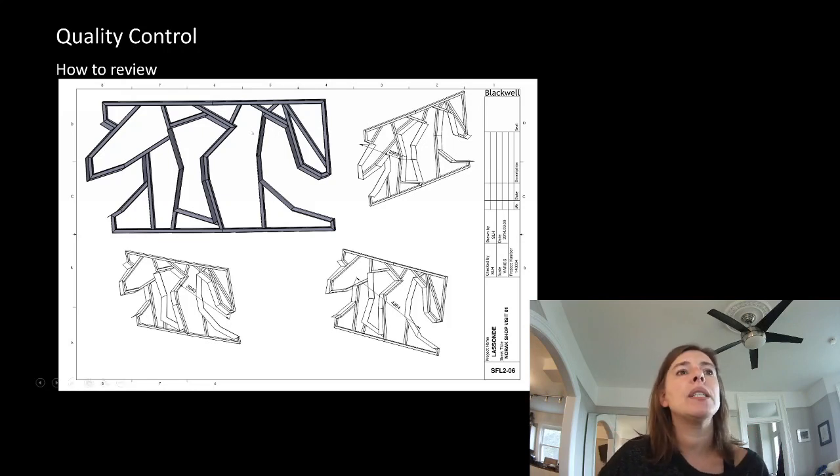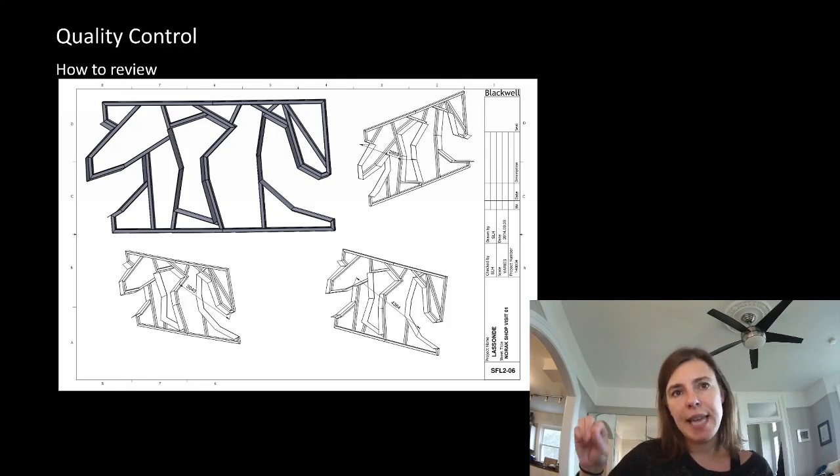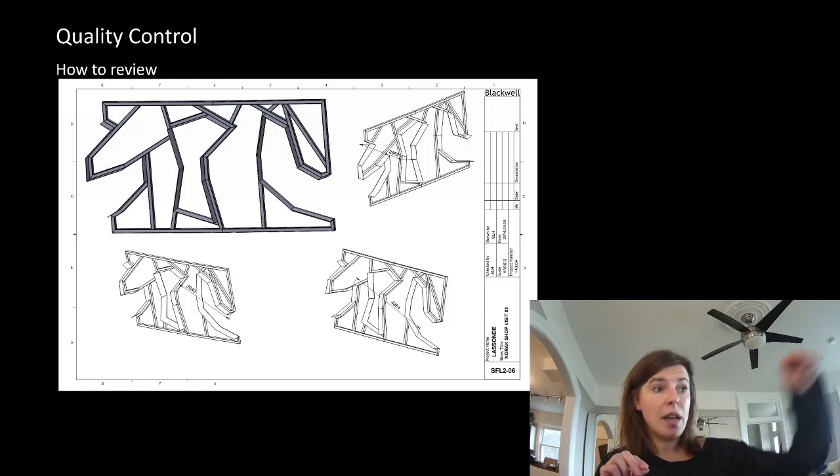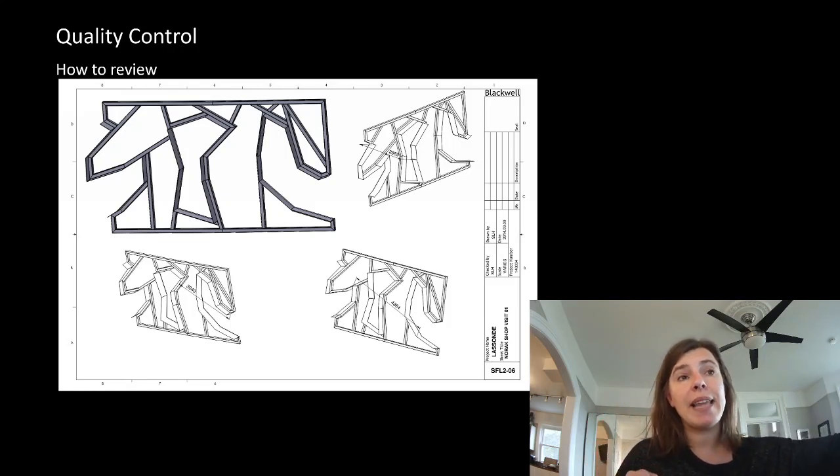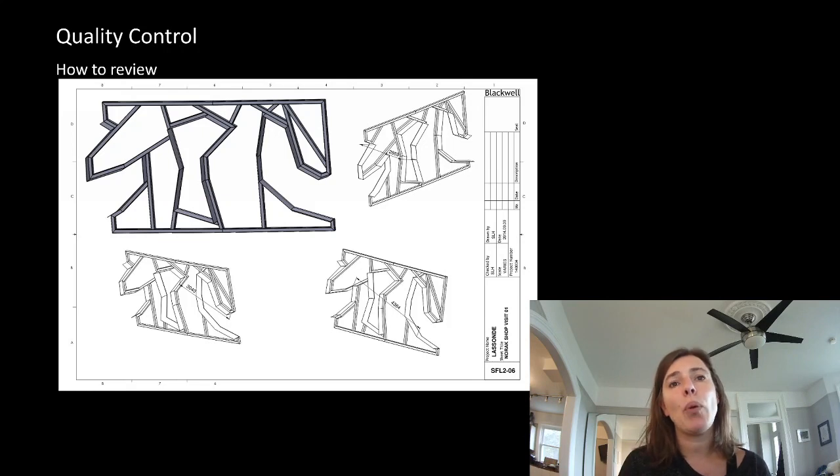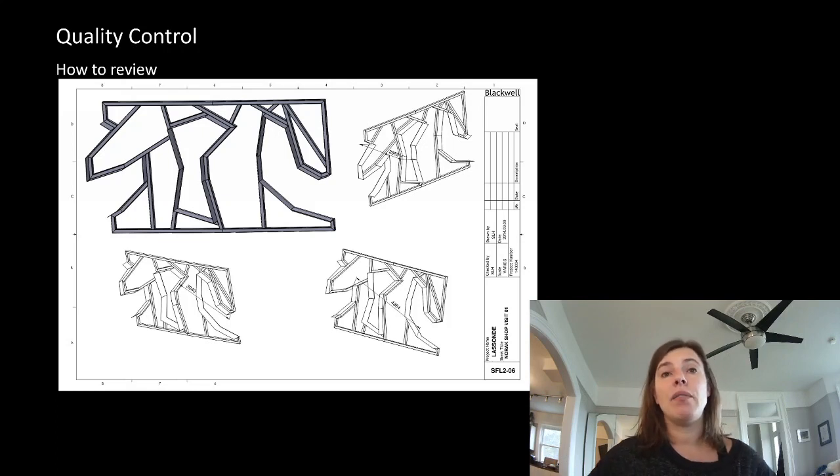So what I determined was that I would pick 3 measurements from the same point, in 3D. And what it needed to be was that a tape measure could touch this point here and pull and measure to that point there. And if we were within 6.4 millimeters of tolerance for all 3 points, we would have met the intent of the 3D model.